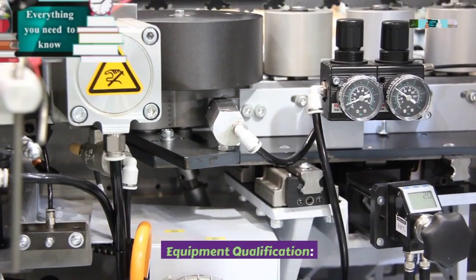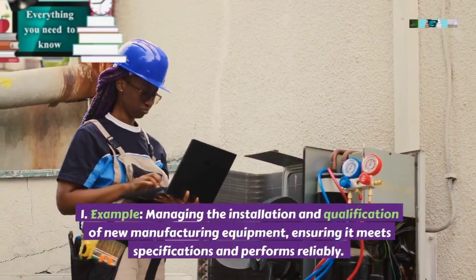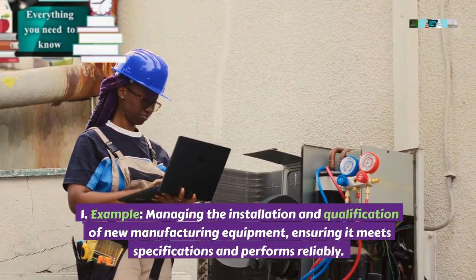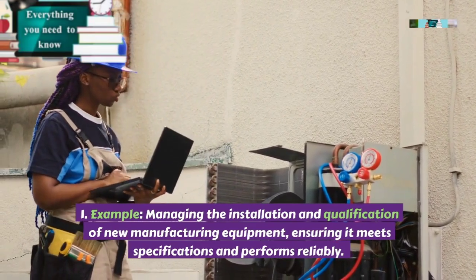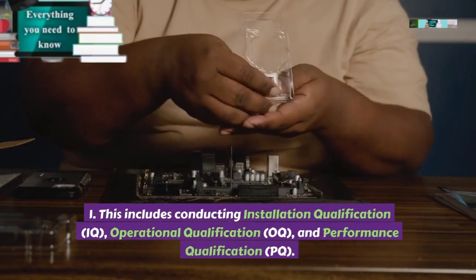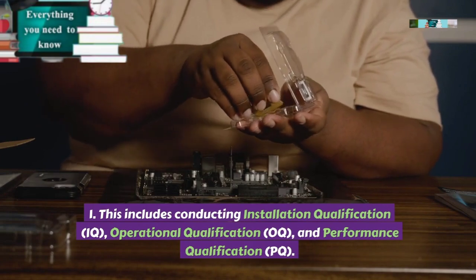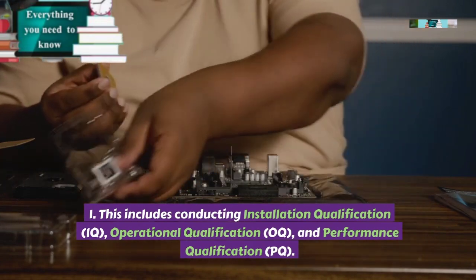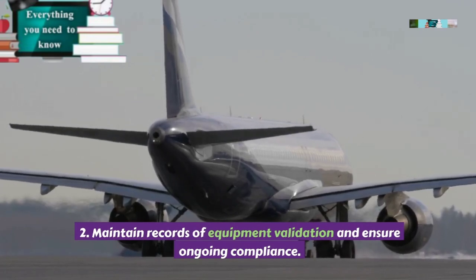Equipment qualification. Example: managing the installation and qualification of new manufacturing equipment, ensuring it meets specifications and performs reliably. This includes conducting installation qualification, IQ, operational qualification, OQ, and performance qualification, PQ. Maintain records of equipment validation and ensure ongoing compliance.